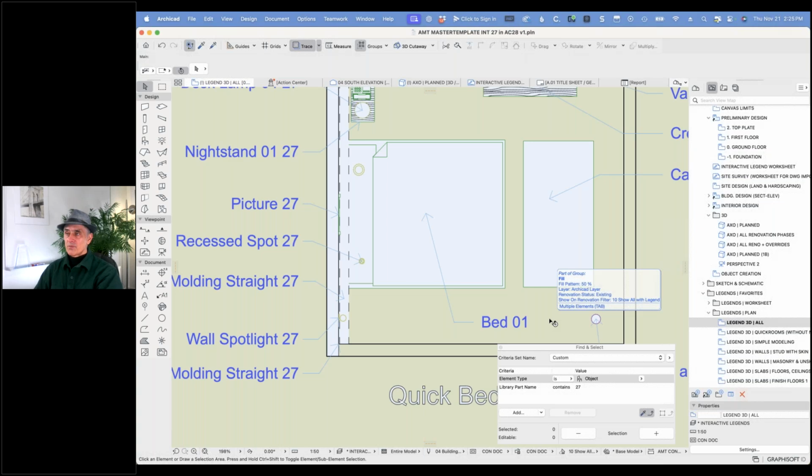So that's some of the basic notes on migrating projects. You have a choice of just saying, I still have 27 or 25 on my computer. My computer runs it just fine. I'm just going to keep working on this project, submit the drawings, put it to bed, it'll stay in 27. You could say, well, I like keynotes in 28. I like this new feature. Let me migrate it to 28, but use the old library. Very efficient, works fine. You can still use keynotes, etc.